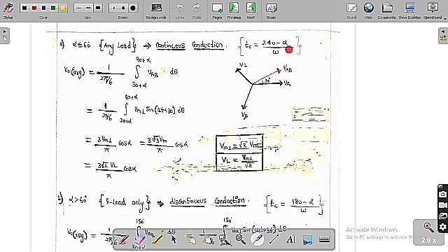There is a small angle alpha, if alpha is increased, for which they are going to face the forward blocking voltage. Therefore 240 minus alpha by omega. You can see clearly that out of 360, 120 degrees is the conduction of each thyristor. So 360 minus 120 is 240. Out of that, alpha is the angle for which these thyristors face the forward blocking voltage. Now 240 minus alpha is the angle for which they face the reverse voltage. So 240 minus alpha by omega.